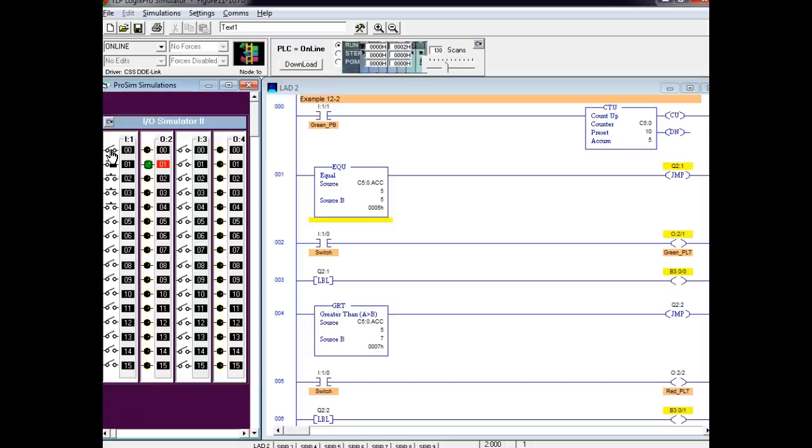We use these things on things that can basically kill people if a relay has problems. At US Steel, we use them on crane magnets. If you lost reset on the crane, if they were radio control cranes, everything would drop out, right? So if you had a load out there on that magnet, what would it do? It would drop it. So magnets were required to use what we call latch and unlatch relays. When you energize the magnet, you latch it, and to drop stuff, you literally had to unlatch it. And the PLC simulates that.